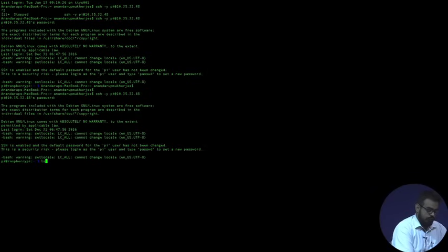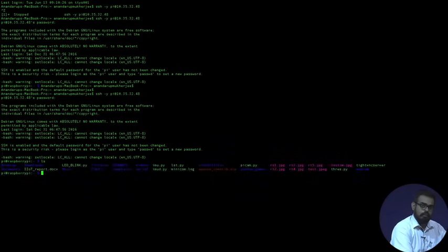So you can just see your file system, what exactly is there. You can give a basic ls command to list files. So these are some of the directories or files within your Raspberry Pi. You can even remotely restart your Raspberry Pi. So for the end of this lecture, I'll just reboot my Raspberry Pi. So I write sudo reboot, press enter.